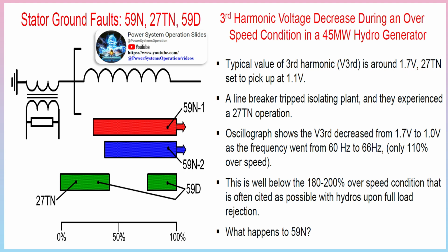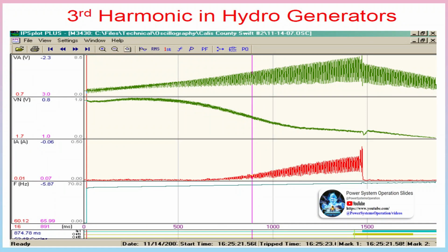Protection against stator overheating. Overloading can cause overheating in the stator winding of the generator. Not only overloading, but failure of cooling systems and insulation failure of stator laminations also cause overheating of the stator winding. The overheating is detected by embedded temperature detectors at various points in the stator winding. The temperature detector coils are normally resistance elements which form one arm of a Wheatstone bridge circuit.